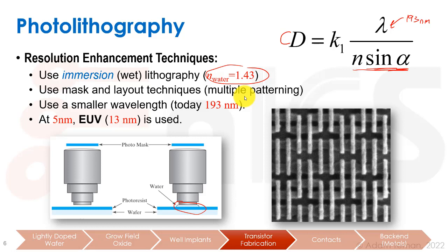By the way, 7 nanometers is not necessarily something that's actually made. Maybe the fins are at such a pitch, but most things are patterned so that gate lengths would be something like 14 to 16 nanometers even in a 7 nanometer process. So the number is mainly a number for marketing. It's not actually what the critical dimension is anymore in these processes. However, it is much smaller than 193 nanometers, and it's pretty amazing how we're able to achieve this.